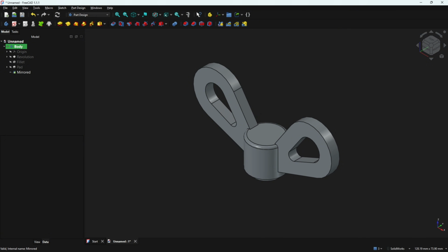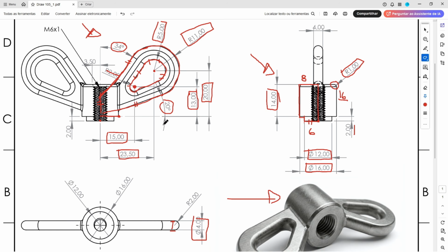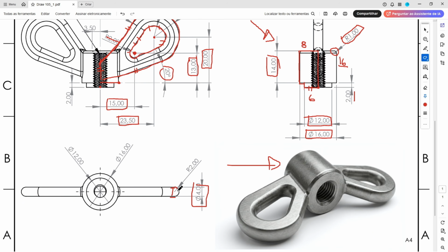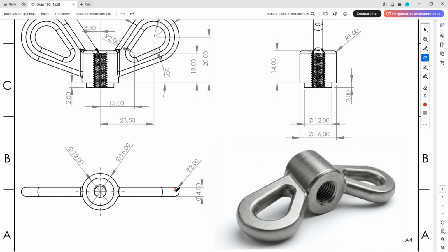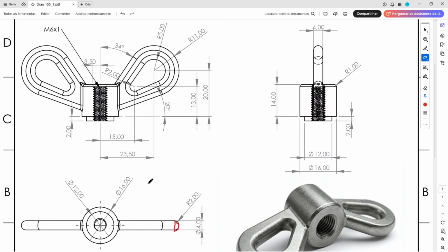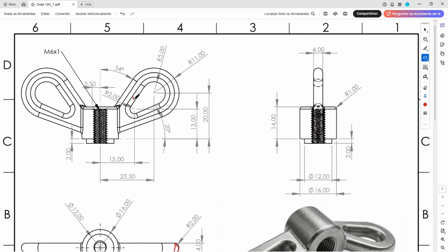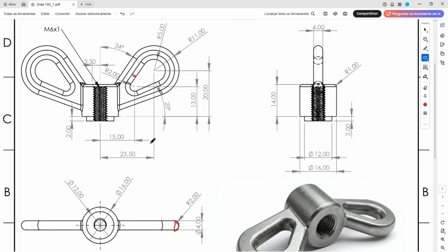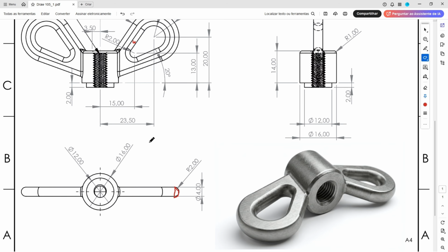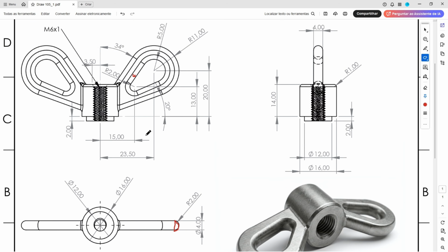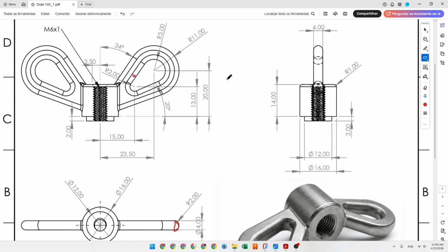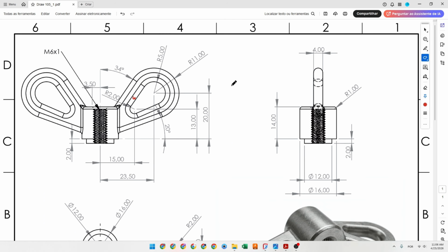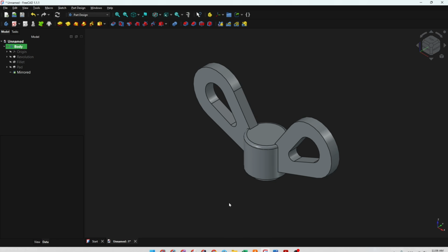and now we have a fillet here. So in this edge we have a fillet with 2 millimeters of radius, or a full round fillet, and inside here we have a fillet with 2 millimeters too. Okay, but we have a problem that in FreeCAD we can't make a full round fillet, so we'll make something. We'll make approximate dimensions. Okay, we will see why we will make this.